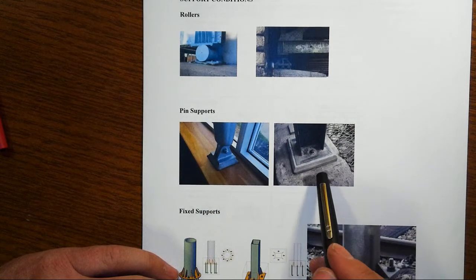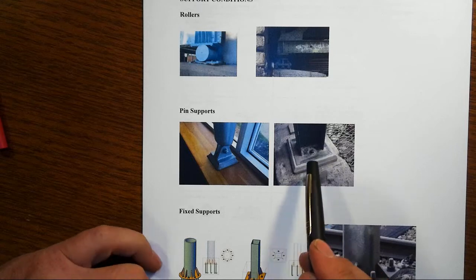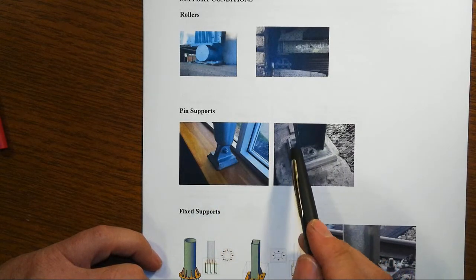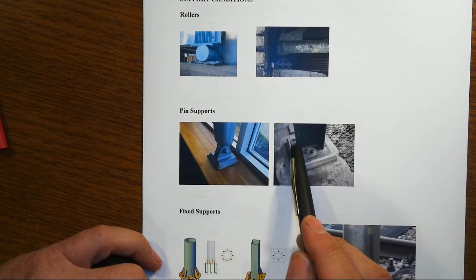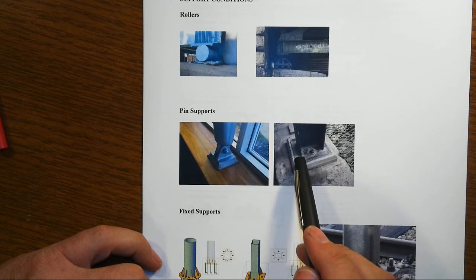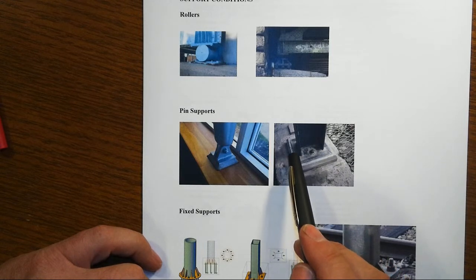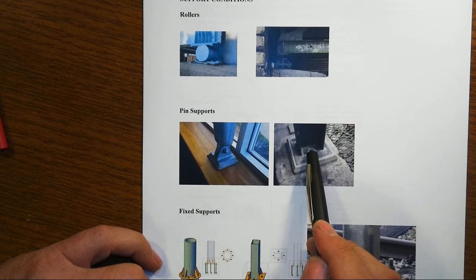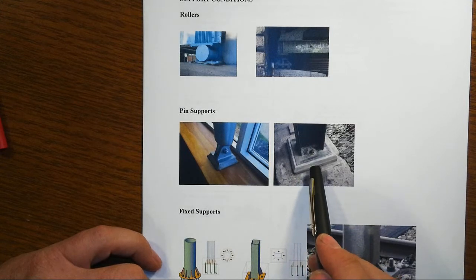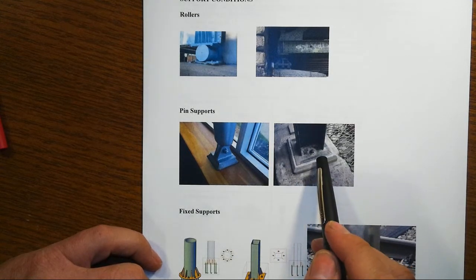Now in buildings, as in the structural columns, instead of a little strut associated with a window, what you'll see at the base of a column is this little wide flange shape. Here's the wide flange, there's a flange here, this is the web. In cross section it looks like an I or an H depending on how you turn it. And we have a bolt here that anchors into the foundation, and one on the other side of the web, just two of them. Right? And that would also be a pragmatic example of a pin support.